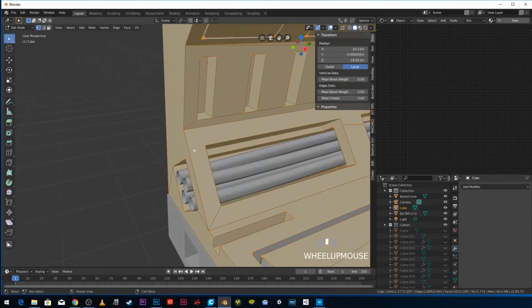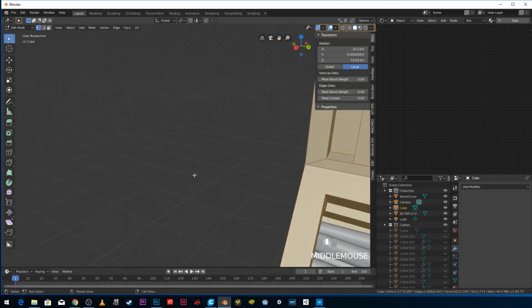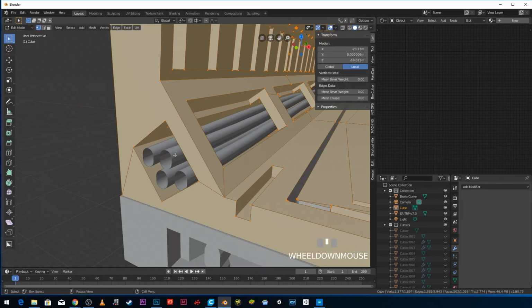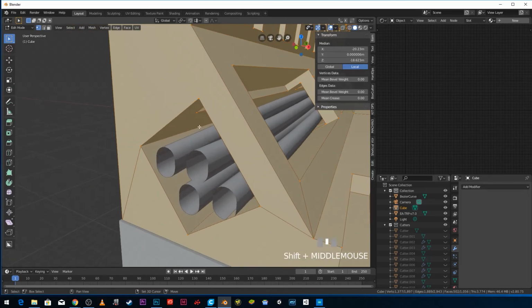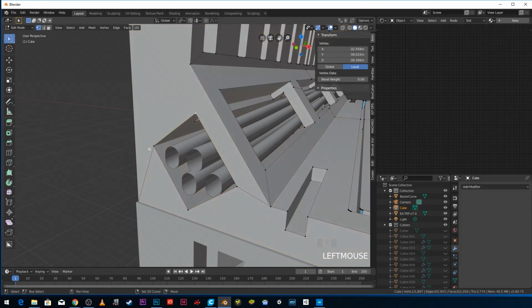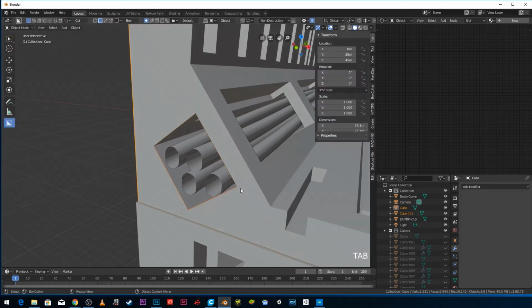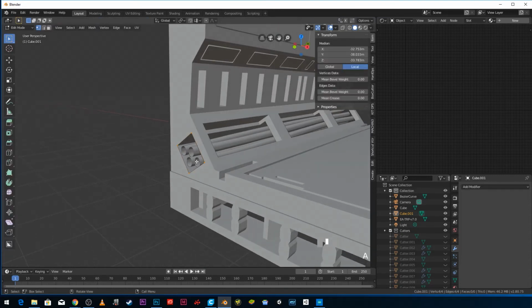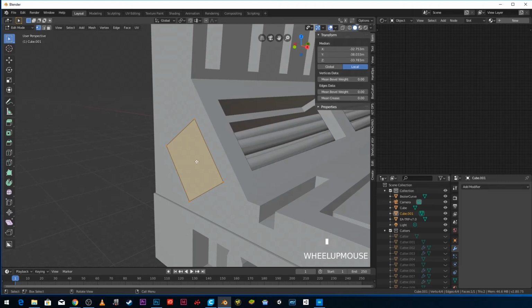Now I can go into edit mode, and you can see that all of those things have been applied. So I'm going to press 1, 2, 3, 4, and go Shift D and then escape. P, separate by section. So now I've made a separate object, which is this here. I can select it and press F and then extrude along it.